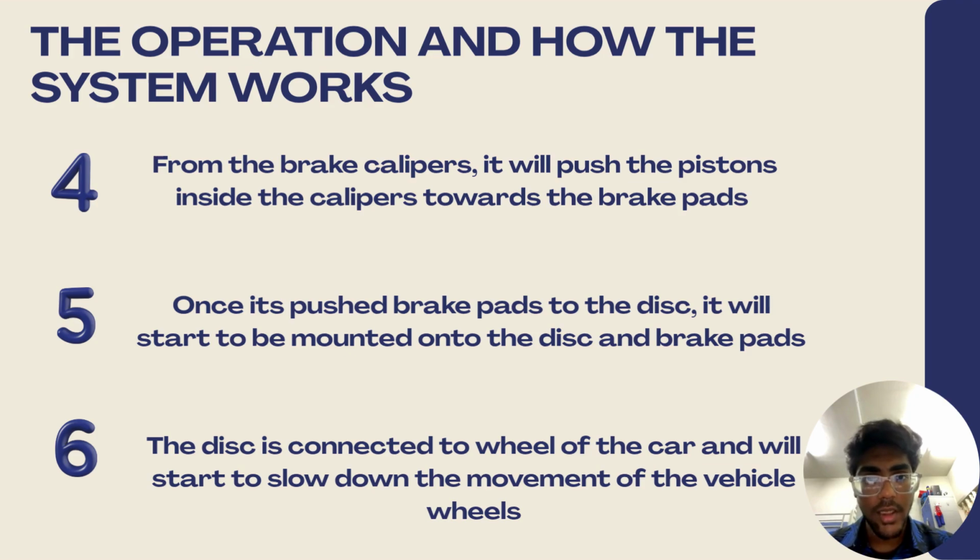From the brake calipers, it pushes the pistons inside the calipers towards the brake pads. Once the brake pads are pushed onto the disc, they clamp onto the disc. The disc is connected to the wheels of the car, and it starts to slow down the movement of the vehicle.